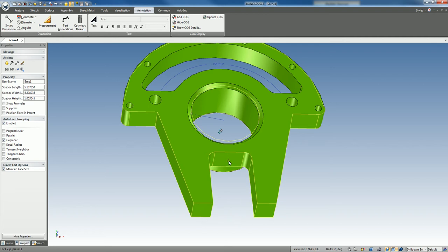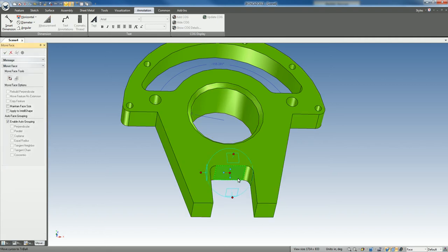You can also just pull these handles, and notice that these are not recognized as blends yet, they're just pure geometry, but even if I pull this handle, notice that face knows how to maintain those associations and moves it with it. You can pull these handles. The downside with pulling the handles, you can only do offset distances inside of here. You don't know the distance. Another way you could do it is turn the triball on, snap it down here, move it off an offset.